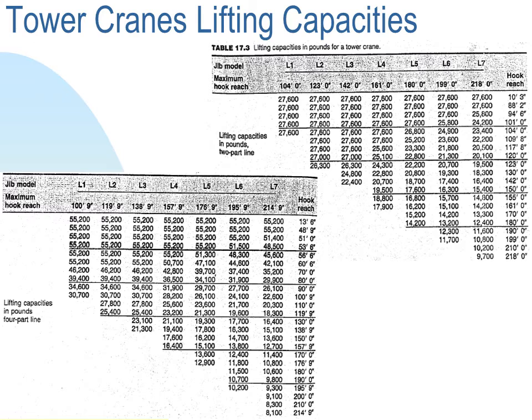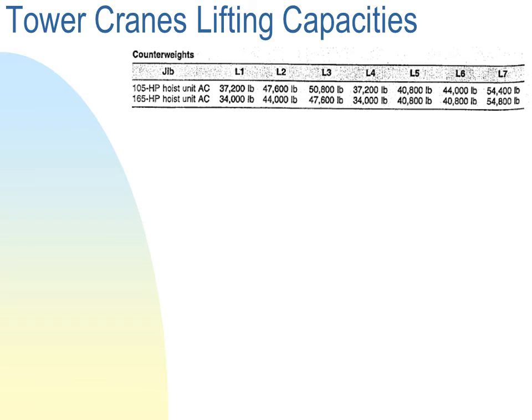And because these low radii represent the case at which a failure will happen due to structural failure, not due to overturning moment, this is why for large radii, maybe 210 or whatever, the differences between these range of numbers are very trivial between the four-part and two-part hoist line cranes. Of course, having different jib dimensions will need different weights for counterweights. So the larger the jib dimension, the larger the counterweights we need.